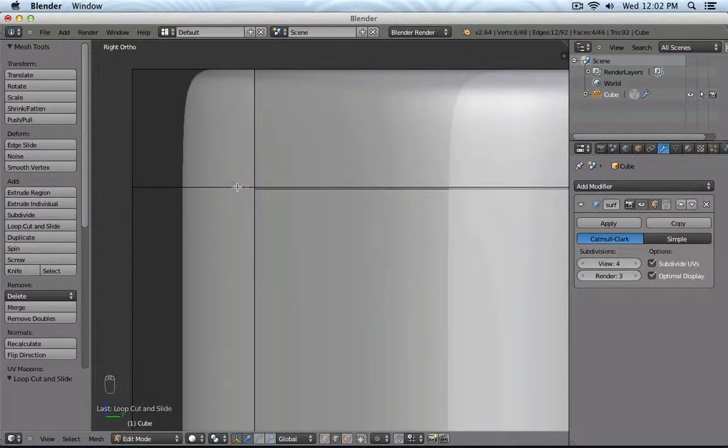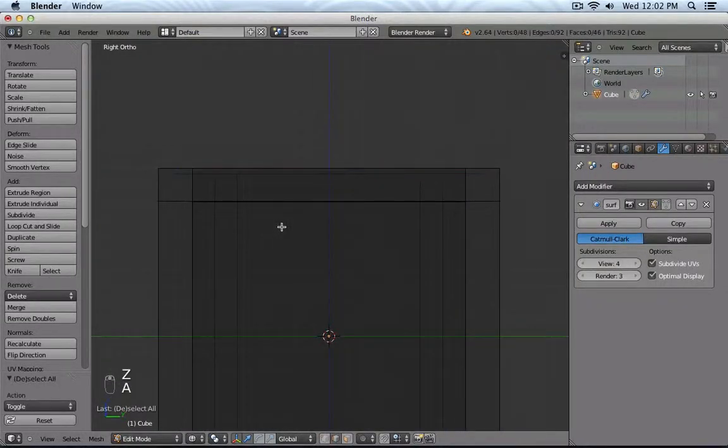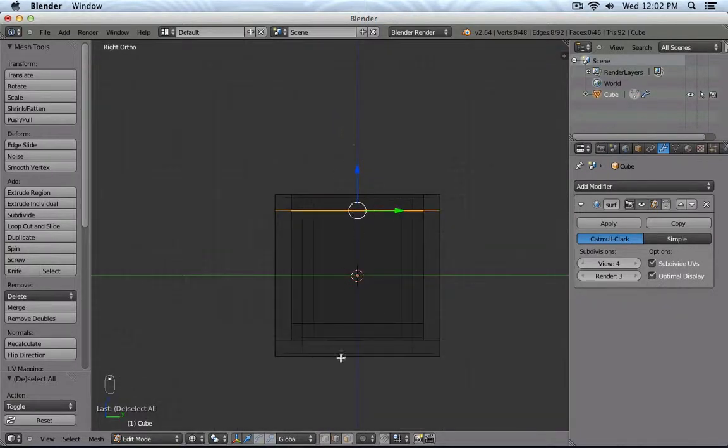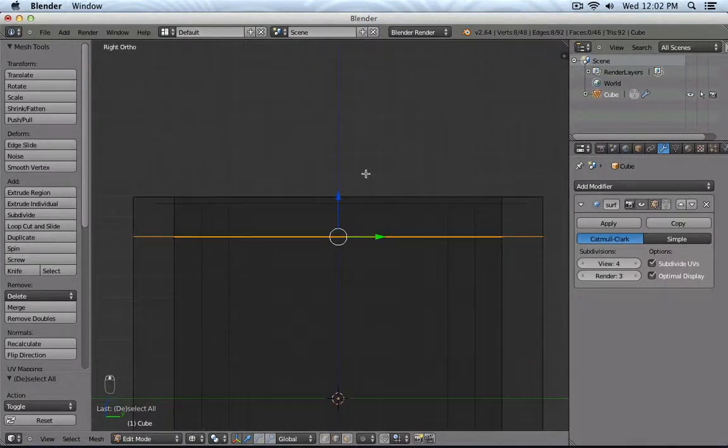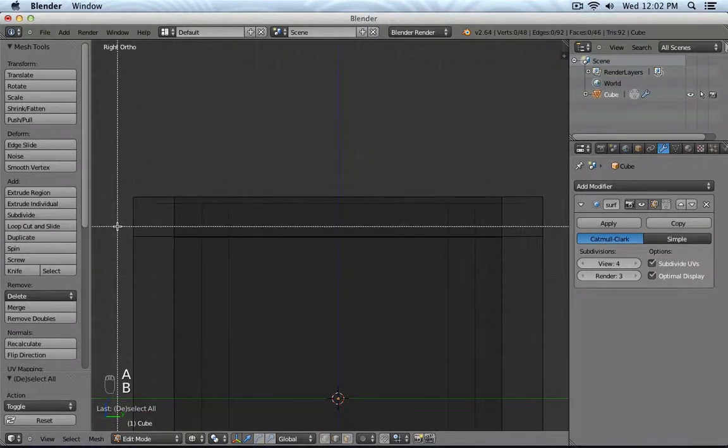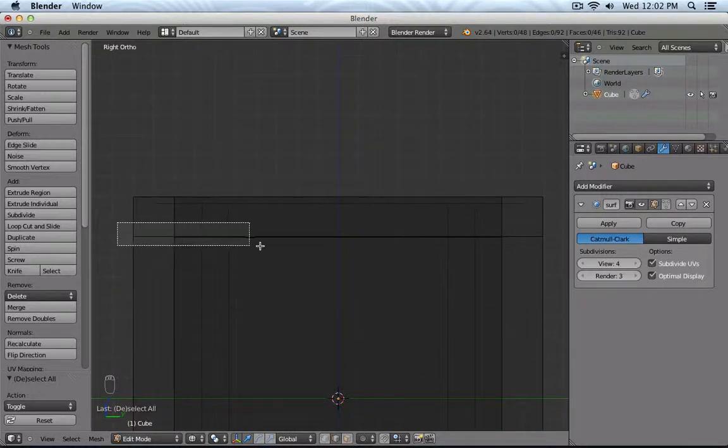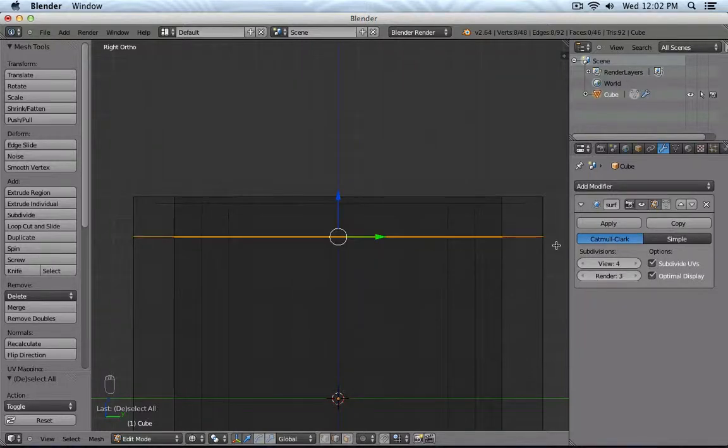Now you see, for example, those 2 loop cuts, they're actually not really at the same height. So how could we adjust those? Well, a very easy way in this case, because this is a nice tubular object, I could, by pressing B in wireframe mode, which I'm in right now, and it also works in shaded mode if you have that view limit turned off, see your cursor turns into kind of like a selection area tool, and then I can drag with left click over those edges and then it selects them.